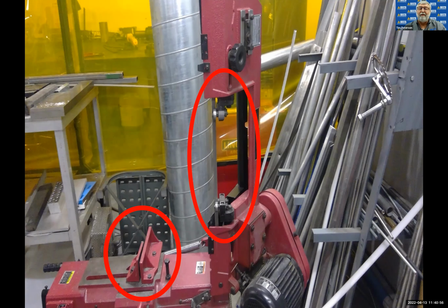Because once in a while, bandsaw blades twist. And if it twists right and snaps, it can create a serious hazard where that guard now is going to prevent that blade from flying out and injuring an employee. So whether it's a horizontal bandsaw or a vertical bandsaw, this is one that gets caught quite often in our inspections, but also in an OSHA inspection because it's right there in front of you.